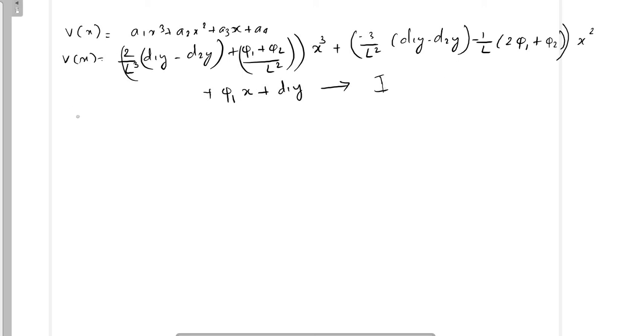So now our idea is to separate the terms in terms of the shape functions n1 d1y, n2 pi 1, n3 d2y and n4 pi 2, because a beam member has member coordinates of displacement as 1, displacement d1y, member coordinate 2 is the slope of that particular node 1, and 3 is the displacement of node 2, 4 is the slope at node 2.